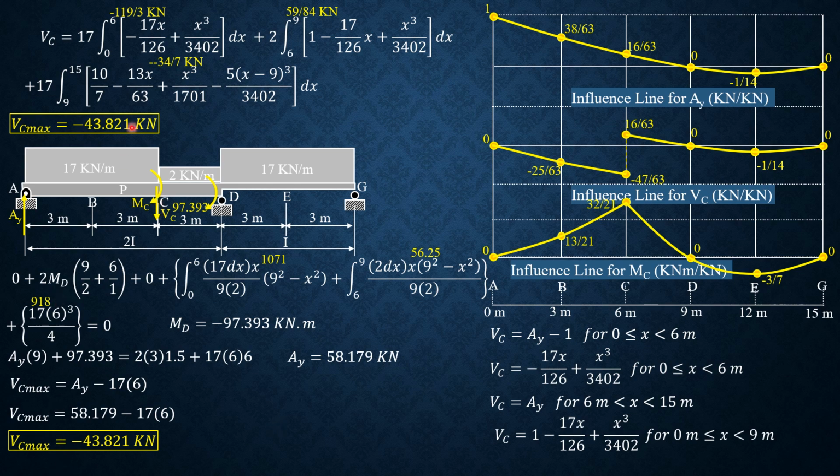So this is by statics, and this is by the equation of the curve in terms of x, but it is a challenging part, and you might forget, because the technique in deriving this equation is based on the deflection equations due to the unit load positioned at the position of the selected redundant. In this case, there's only one redundant, so it's easier. Then after we derive that, we don't need this equation.